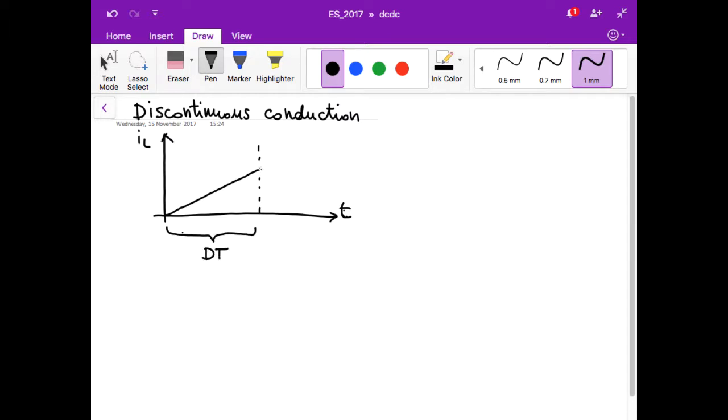During T off, the current in the inductor decreases. The current passes also through the diode, so it cannot go below 0. If it tries to go below 0, the diode goes off, and the current therefore goes to 0. So we have two different times, which we can call delta 1 T and delta 2 T, during T off.